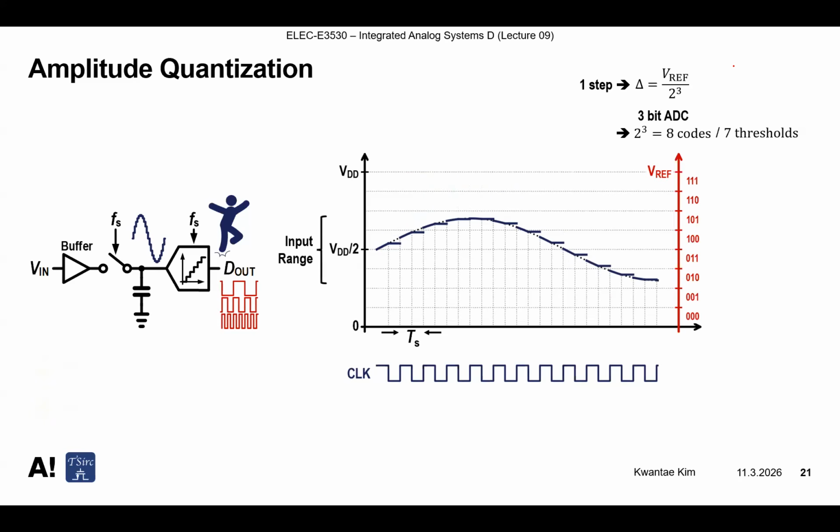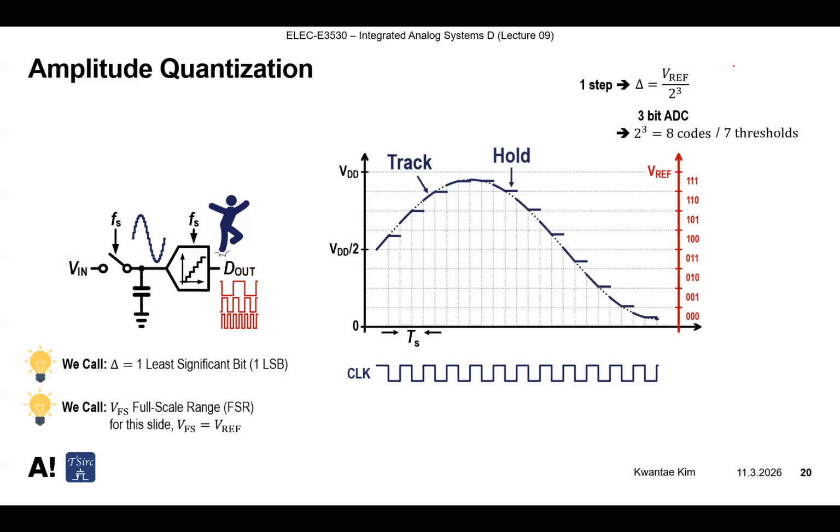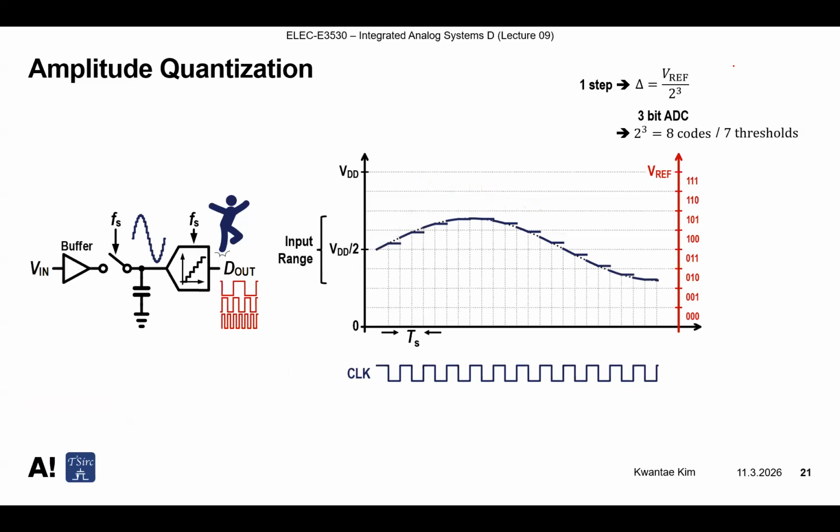But of course, there can be some cases. I mean, this case is definitely where the input signal is as large as from VDD to 0 volt. So its analog input signal is quite a large signal. But you probably remember your amplifier design, CAD exercise 3, such that its input linear range, or input DC range, if we set it as a buffer, then the input DC range is equal to the output DC range, because the output follows the input, right?